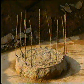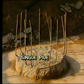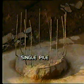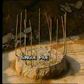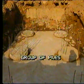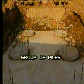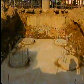The pile is always cast some length above the desired level and cut at a later stage to bring the pile to the desired level of the pile cap. This is done because the concreting in the top portion of the pile may get disturbed, which otherwise would reduce its load carrying capacity.